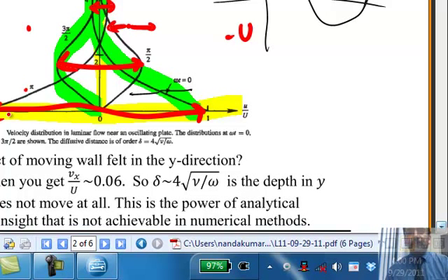So the momentum diffusion is going forward for a while and then it's going backward. So you're not continuously adding momentum transfer diffusion in one direction, like you would when you're moving the plate in the same direction. That diffusion can go all the way to infinity. But in this case, because there is a reversal, there is a finite distance by which the flow will penetrate, and beyond that the fluid does not know that there is a plate and the plate is oscillating. I can ask you to find what the distance is for a given fluid at a given frequency. You should be able to do those kinds of analysis given the solution.